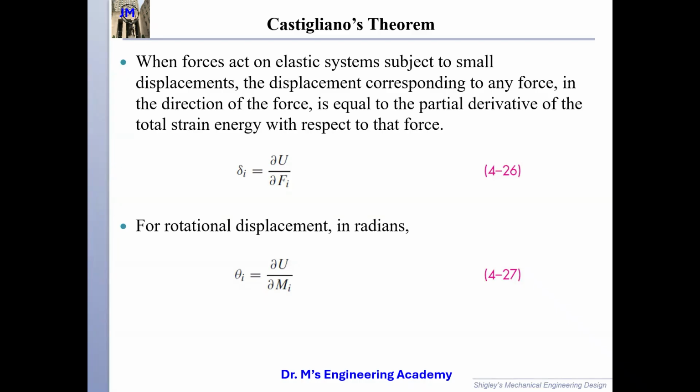If you do not have an actual force or moment, you can still use either of these two equations to get the displacement or theta. How to do that? You can just assume you have a load, but finally, after you take the derivative, you set the force or moment to be zero. Then you get this delta i.